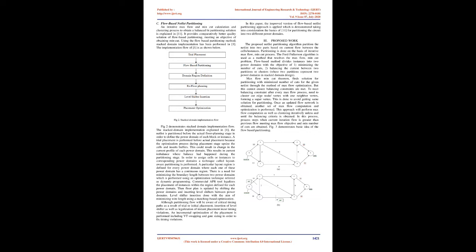Vertices are weighted. A gain function helps in partitioning a set of vertices into 2 parts while maintaining minimized number of hyper-edge cuts and balanced weights. FM algorithm adds new features to KL heuristic. Improvements to the FM and KL algorithms have been proposed, such as multilevel K-way hypergraph partitioning algorithm, which substantially improves the existing KL algorithm [10]. Multilevel extension of FM-based partitioning technique, in which optimal placement and partitioning algorithms are developed based on gray code-based enumeration and branch and bound [9].